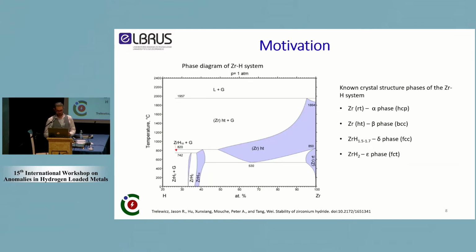We have here, and I'm going to present very shortly, this phase diagram. So zirconium has a very special feature. It changes a lot its crystal structure. There is almost every single crystal structure you can find into that phase diagram, which makes the tracking of the forms of hydride at the same time difficult by some means, but also reassuring, because when you have identified the crystal structure, you know where you are on that graph.